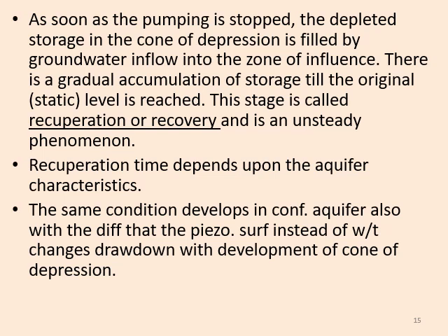The same condition also develops in a confined aquifer, with the difference that instead of the water table we have considered in the unconfined zone, in the confined aquifer we have to consider the piezometric surface that changes the drawdown with the development of the cone of depression.